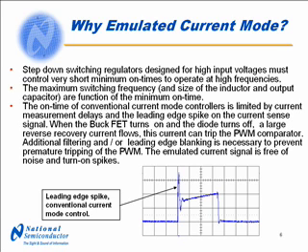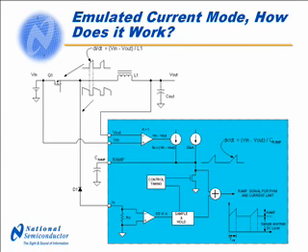An emulated signal is free of this noise and turn-on spikes. Shown on the slide is a typical measurement of a buck switch turning on in a buck application. Shown on this slide is a buck regulator power stage comprised of Q1, D1, L1, and Cout. The objective is to create a signal that accurately represents the current through the buck switch Q1 without actually making a direct measurement.